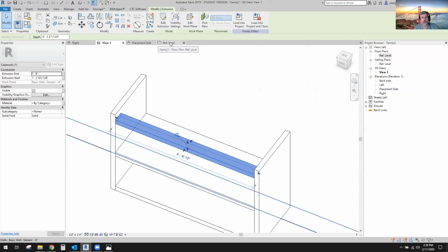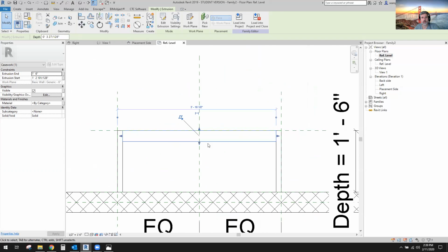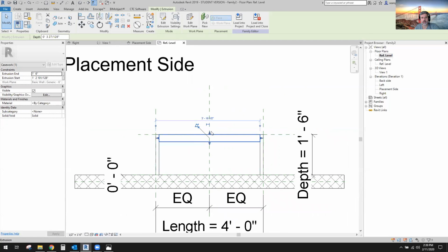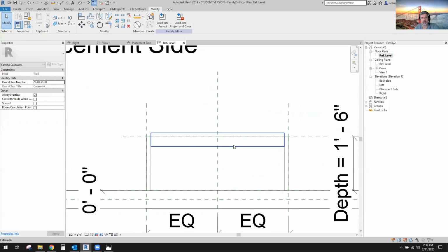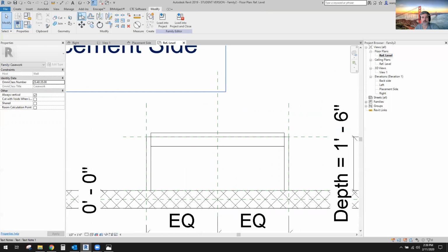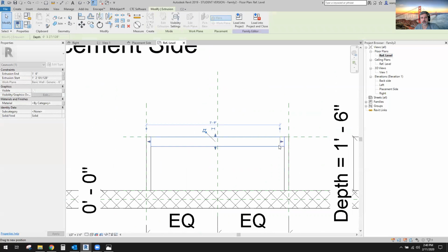And then in the reference level here, what I'd like to do is, I can't edit that downwards, so I'll need a reference plane to control that thickness right there. Currently, it's locked into place. This, nope, it's not locked into place because I copied it. All right, so I need to lock the front of it to that plane, locked. Also, these sides are not locked at the moment. Do you see that? When I pull it away, it's not locked.